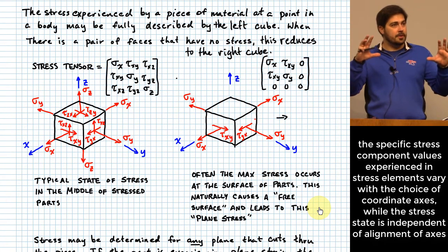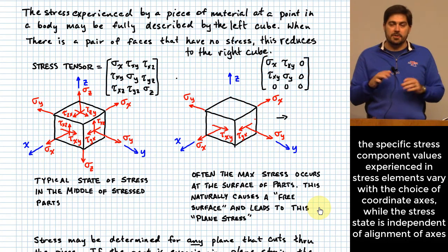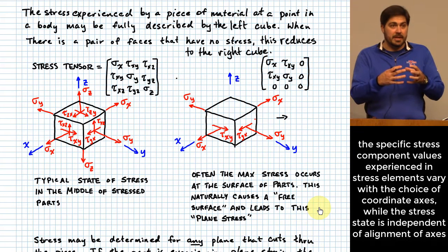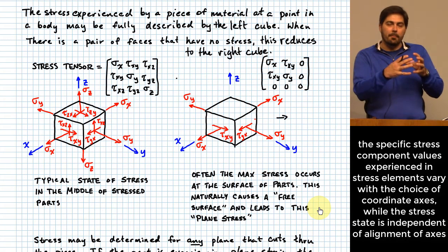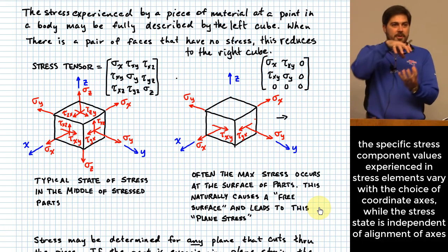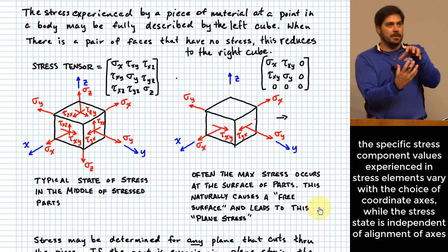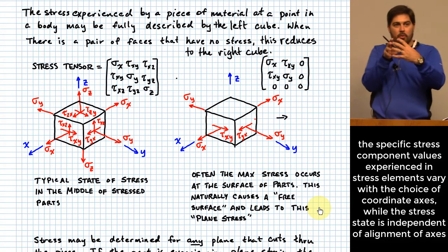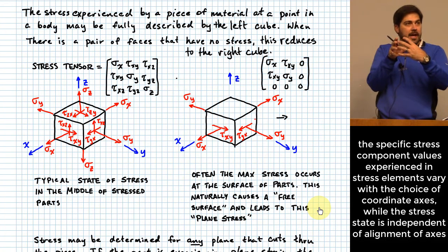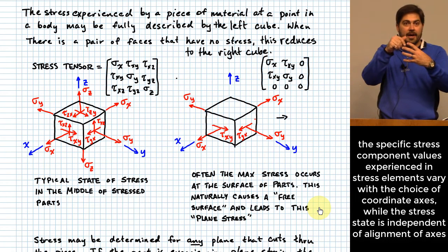on the whole theory. And the reason that stress transformations are important is a state of stress sort of is what it is, but it will have numbers that are associated with that state of stress that vary depending on the coordinate system that you use, right? So if you define a little element of material so that it's aligned according to one coordinate system, and that piece of material has a state of stress in it, that state of stress is the same as if you had a different set of coordinates, even though the actual stress components that you would identify change.